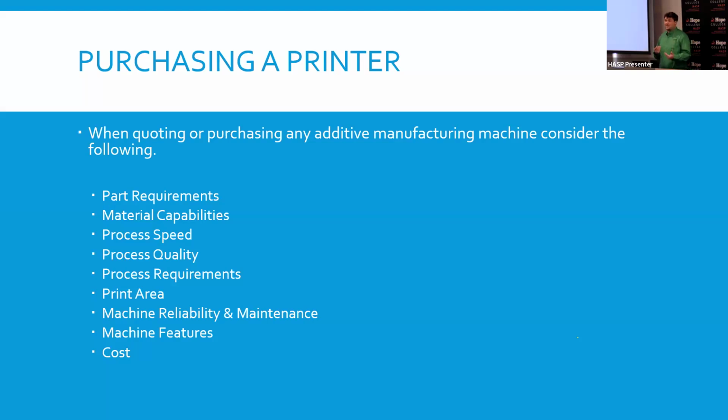So if I'm going to buy a cheap FDM printer, it's going to require me to level that bed manually. So if I have it like this, shift it over this way, I have to manually go underneath it and then push it up like this. So there are 3D printers out there that have auto bed leveling features so that you don't have to worry about that.